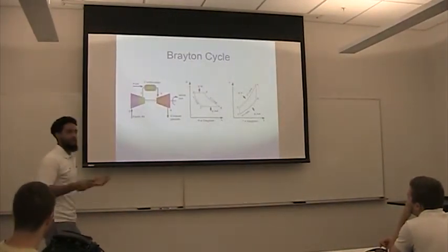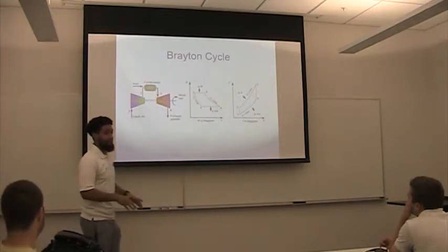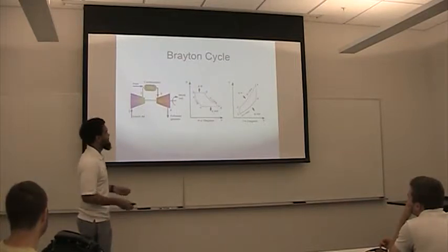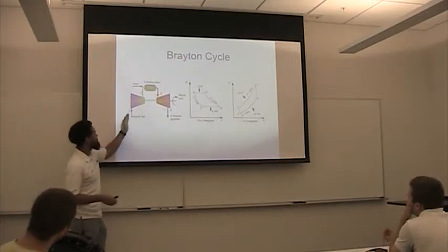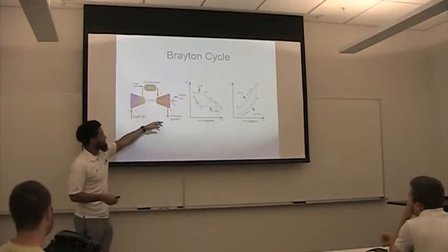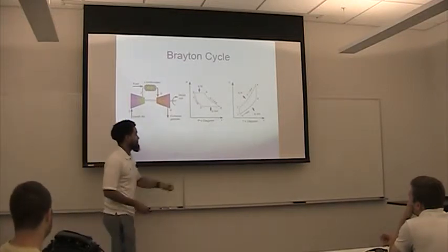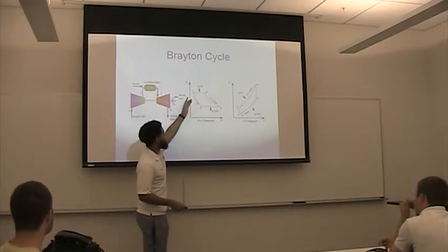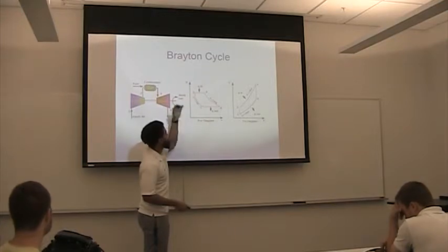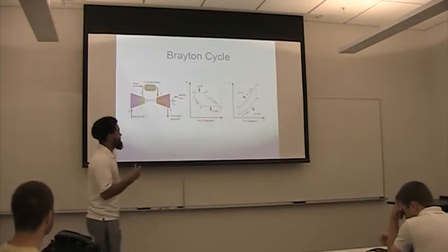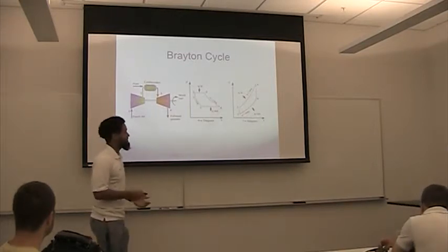So how does this work? All this was theorized, or the beginning of all this was the Brayton cycle. And this cycle is most famous for explaining how fresh air goes to a compressor, goes to combustion with fuel, then turns a turbine to get some work out. And you have exhaust gases, of course. So according to this PV diagram, starting at 1 and going to 4, 1 to 2, the S is constant, P is increasing, then 2 to 3, you have the Q_in, which is heat, but the pressure stays constant. 3 to 4, S is constant, but you decrease in pressure, and then 4 to 1, the Q goes out, and that's all that heat, the exhaust gases.